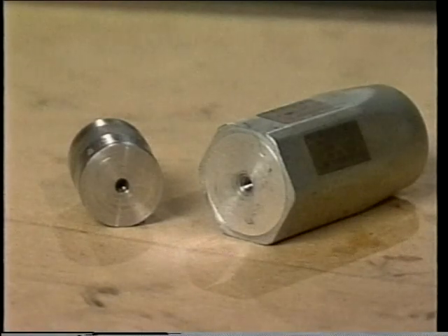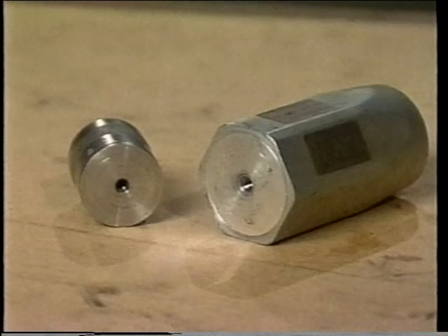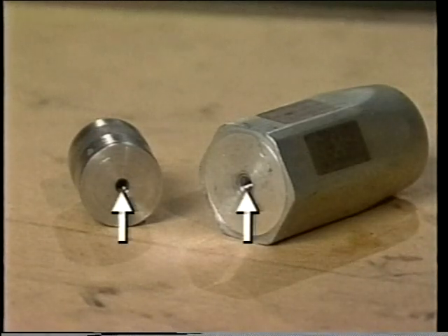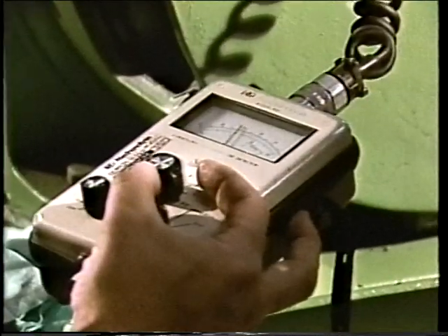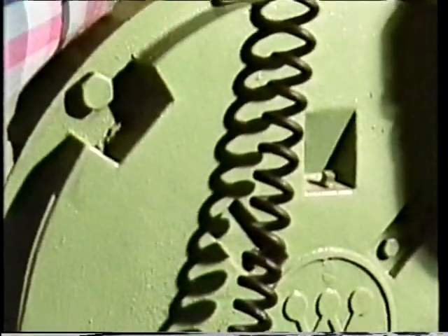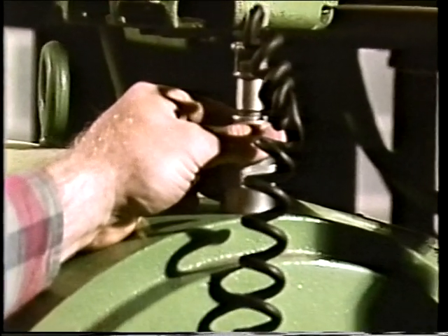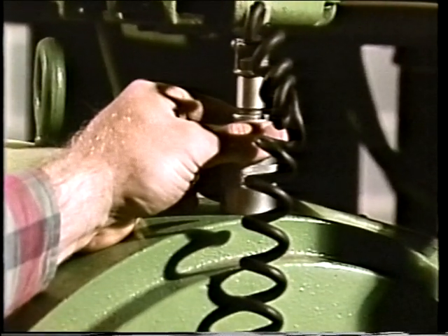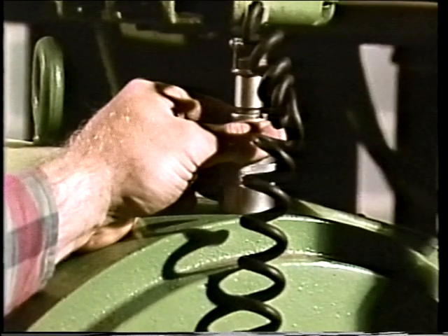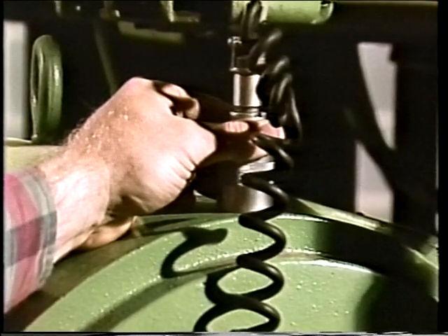One of the most successful mounting techniques involves bolting the pickup onto the machine being checked. Many pickups are designed with a threaded bolt hole just for this purpose. Unfortunately, nearly every mounting procedure has some limitations. For example, holding the pickup in place can prevent the accurate measurement of higher frequency vibrations, and bolting the pickup onto the machine can be time-consuming.